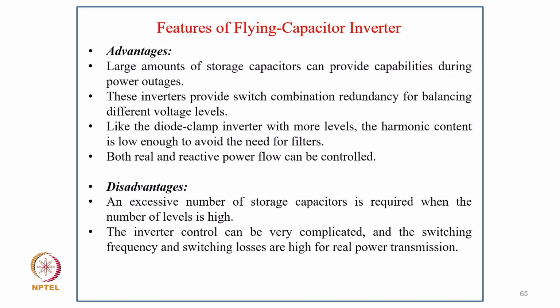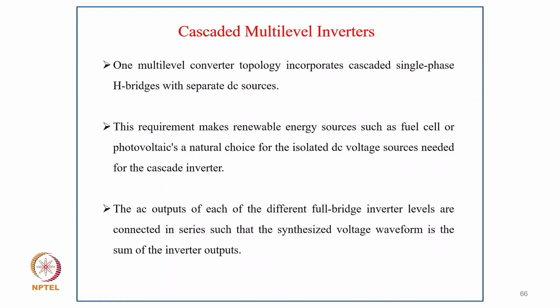The disadvantage is that an excessive number of storage capacitors is required when the number of levels is high, and the inverter control can be very complicated, and the switching frequency and switching losses are high for real power transmission.